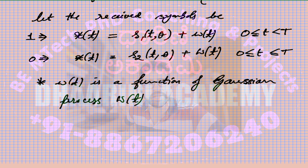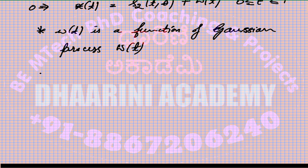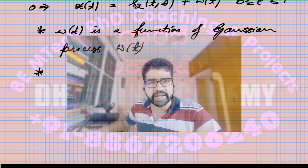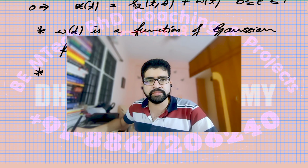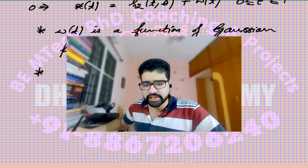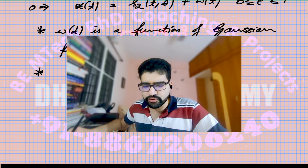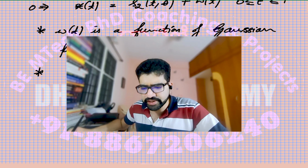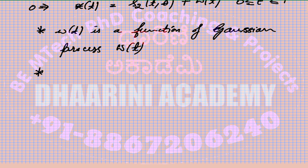Again, we come back to the basics of orthogonality. Since S1 of t and S2 of t are both supposed to be orthogonal to each other, we have to choose phi 1 of t and phi 2 of t in such a way that they have unit energy and they are orthogonal, so you call them orthonormal basis functions.